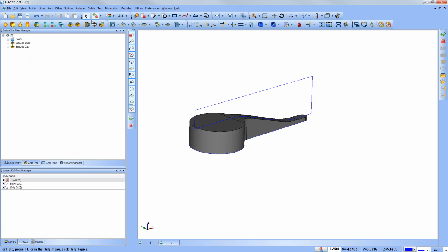As far as making mold type parts, there's a number of ways to do it. If it's something symmetrical that you can revolve, maybe you're using a revolve cut, which I haven't set to go over on this webinar, but extrude cut you could use for that. Yes, you just set the depth. If you're not going all the way through, then you'd be setting the depth up to which you want to remove that material.